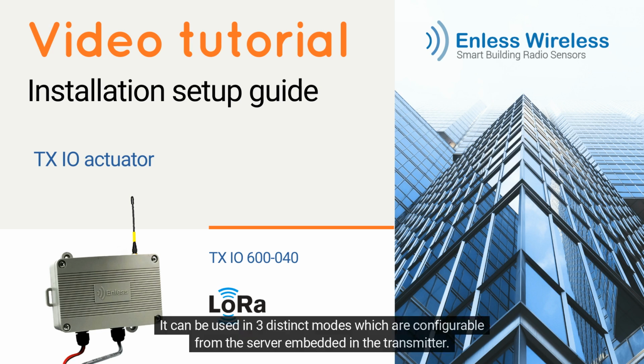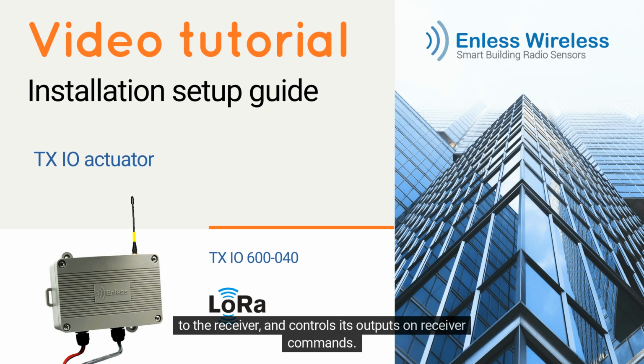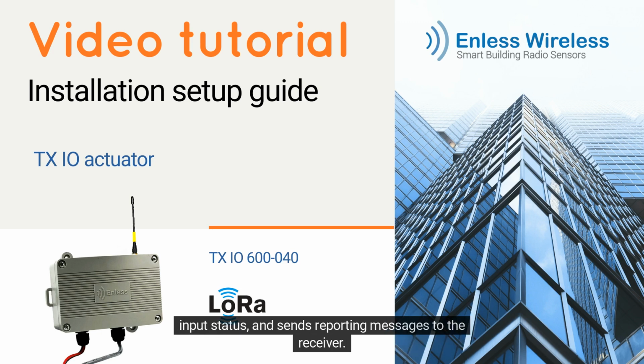It can be used in 3 distinct modes, which are configurable from the server embedded in the transmitter. We will start with the remote control mode, where the TXIO transmitter reports the status of its inputs to the receiver and controls its outputs on receiver commands. Next, we will configure the TXIO in local control mode, where it controls its outputs according to the input status and sends reporting messages to the receiver.